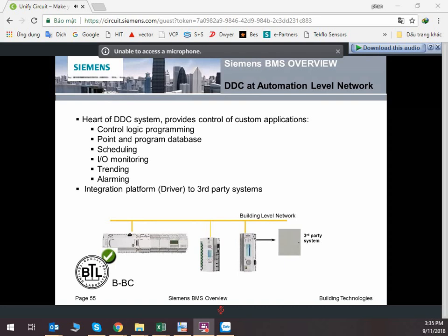We do have a driver for BACnet MSTP. They are for special applications. But usually our FLN, we can actually connect to third-party BACnet MSTP devices directly. So we do not need an integration driver. So far, most of you will order the Modbus driver. That's all, which I will cover later on in my slides.